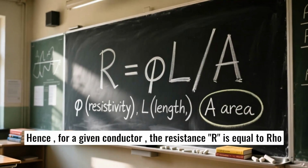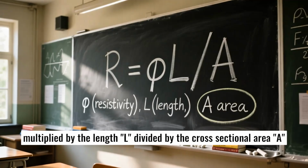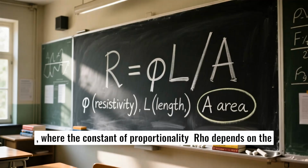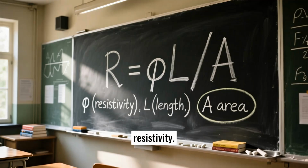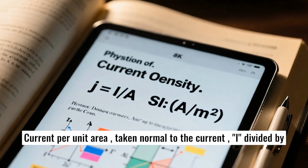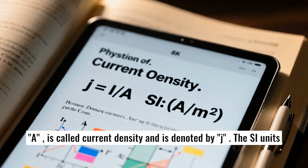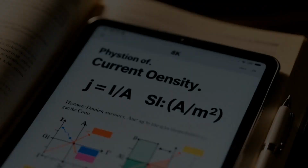Hence, for a given conductor, the resistance R is equal to ρ multiplied by the length L divided by the cross-sectional area A, with a constant of proportionality ρ that depends on the material of the conductor but not on its dimensions, called resistivity. Current per unit area, taken normal to the current, I divided by A, is called current density and is denoted by J. The SI unit of the current density is A divided by meter squared.